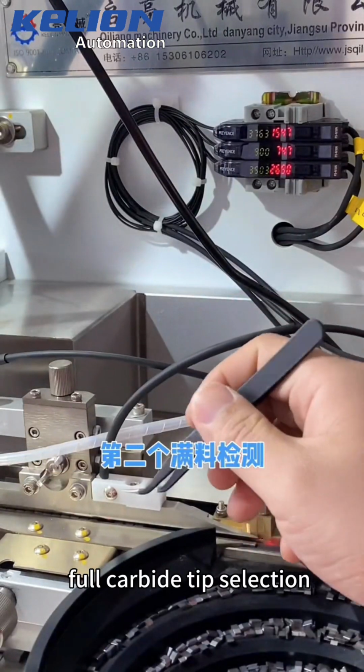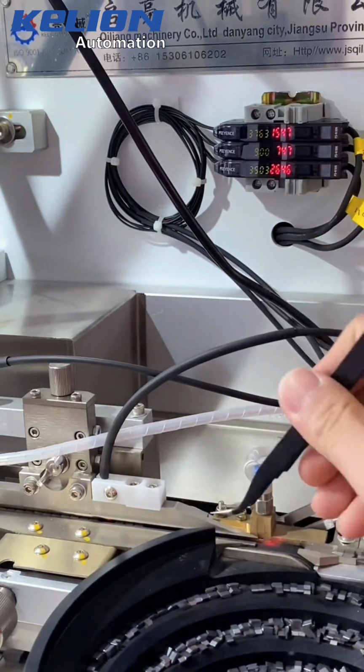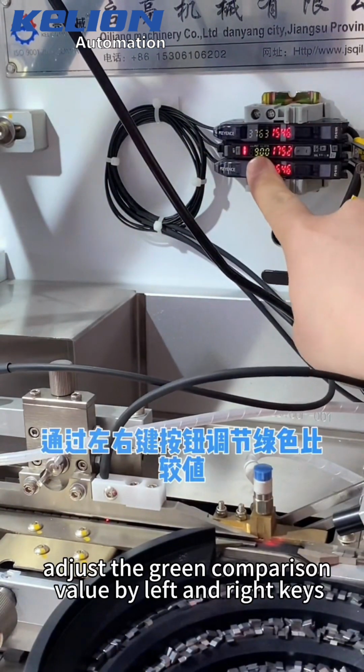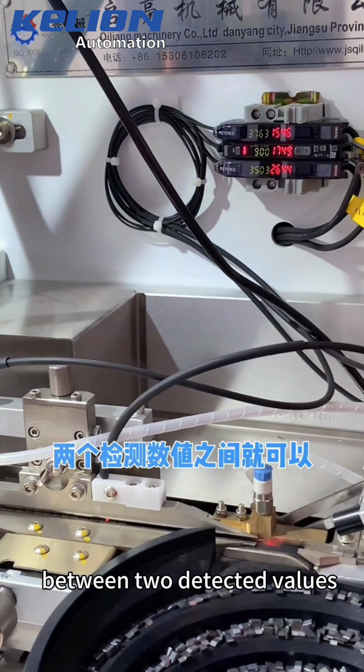Full carbide tip selection. Firstly, look at the detected value without a carbide tip under the lens. Then look at the detected value with a carbide tip. Adjust the green comparison value by the left and right keys, and adjust it to between the two detected values.